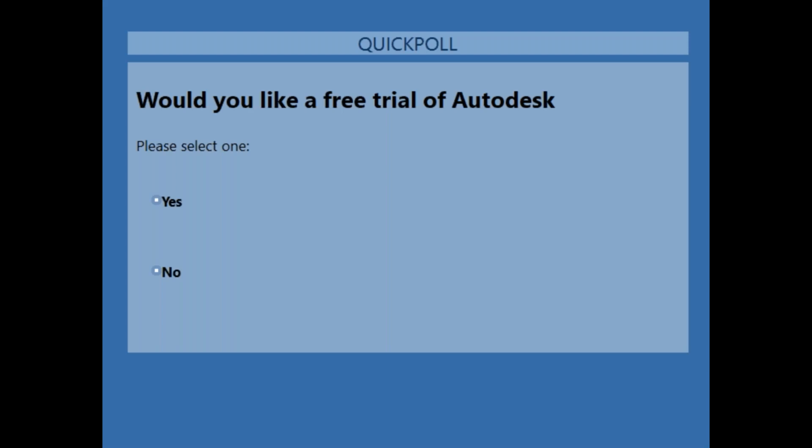Once you do that, obviously you can make any adjustments based on any changes that happened during the new plan revision. And on the 3D side of things, once you run that updated revision into Autodesk Takeoff, you'll be able to see a full analysis of all the quantities that have changed. From there, you can either choose to accept those changes and carry them forward, or you can choose not to accept those changes and walk through that takeoff process again.